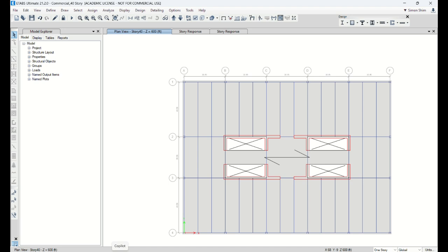X direction is stiffer, Y direction is stiffer. Overall, when you look at this as a two... X direction is stiffer, right? Do you see that? Because this is the strong axis. Now, when this direction is smaller but you have a very long core, it is stiffer, right? But in the Y direction the building width is bigger, while your core wall advance is this one. So if you see this as a cube, which one obviously is going to suffer more? Obviously in this direction: more wind load, less stiffness.